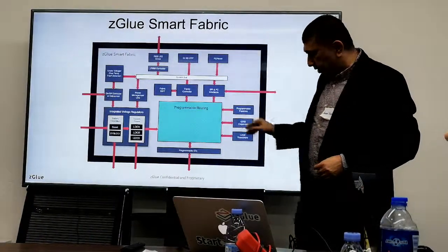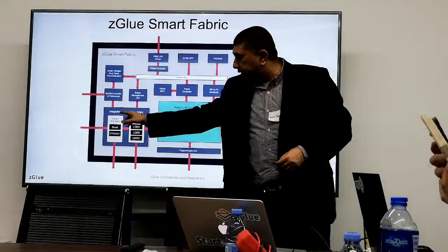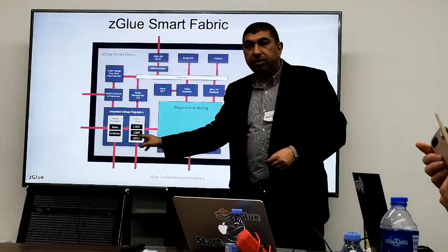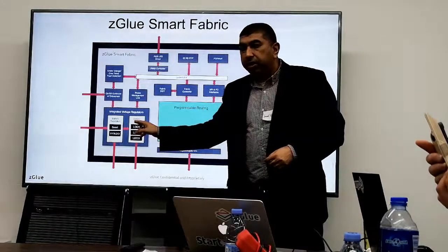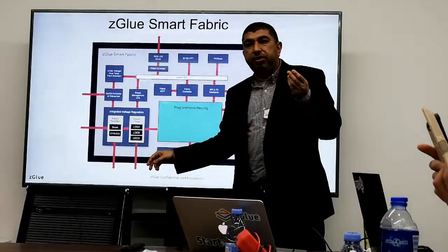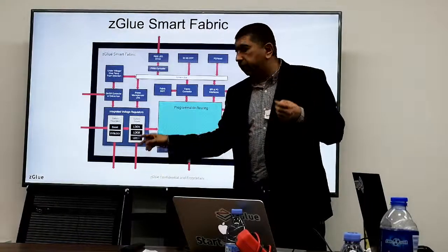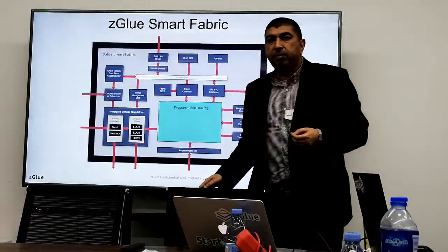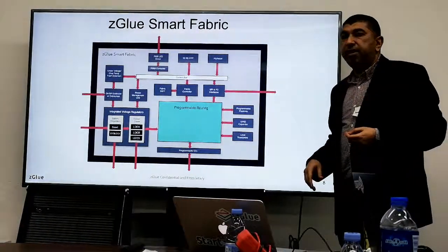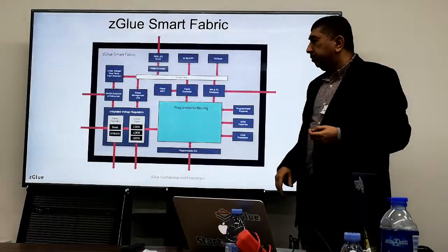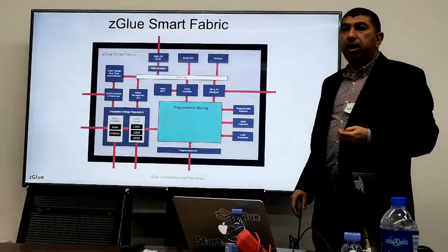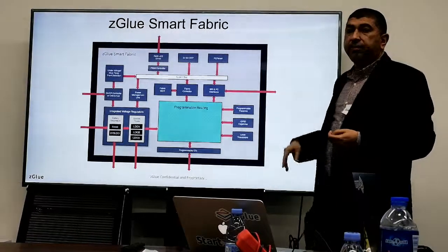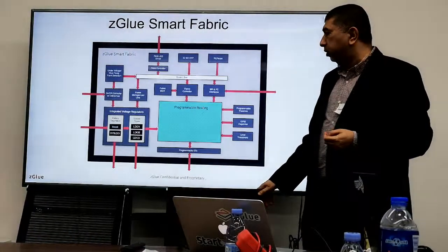Inside the chip, there are all these other things. Like I was saying, there are integrated voltage regulators, LDOs of different kinds that generate anywhere between 3.3 volts to 1.8 volts, 2.5 volts. We have boost converters, system level LDOs. Our next generation will have buck converters. This particular design can handle up to 500 milliamps. For this particular design, we have other things in the works as well.